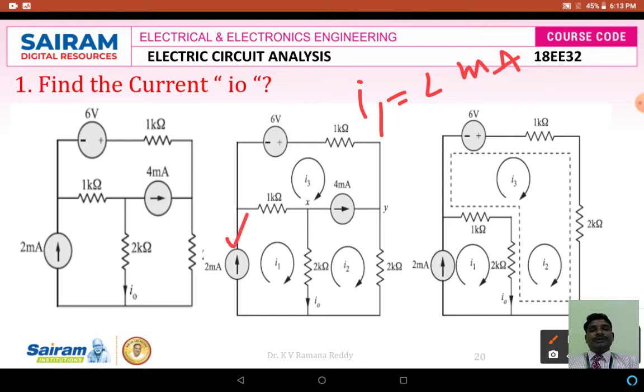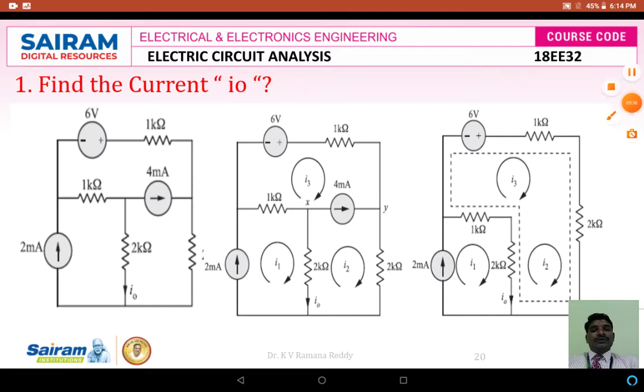by looking at this circuit. Similarly, if you look at loop 2, the current flowing in loop 2, that is I2, is equal to 4 milliamperes, which we wrote using the direct inspection method. Next, whenever we look at this circuit, I2 is the current flowing as 4 milliamperes, but I3 is the current which is flowing opposite to this 4 milliamperes.